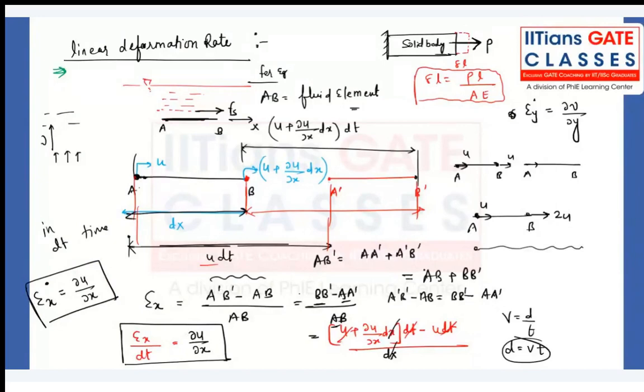Just think of AB as a solid body which is being deformed just because of the velocity differences. Because unlike in solid mechanics, here you cannot say the deformation purely based on the force, because force is acting the same on particle A and particle B. That is a shear force. Let's suppose here we have some fluid plate, which is moving with some velocity v by the application of force. So this is Fs, and they will offer Fs like here.